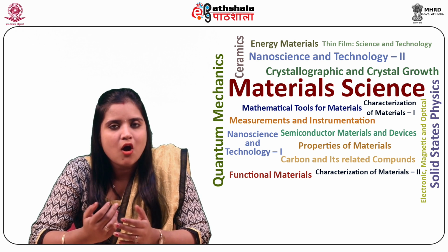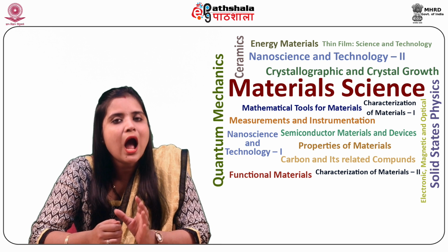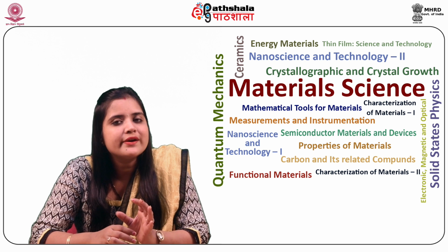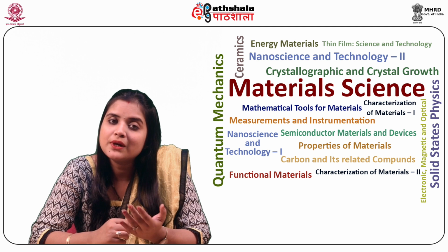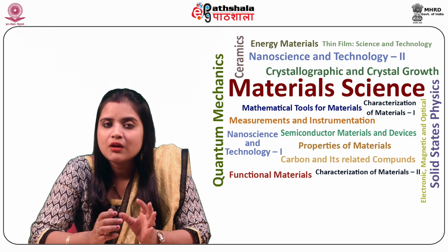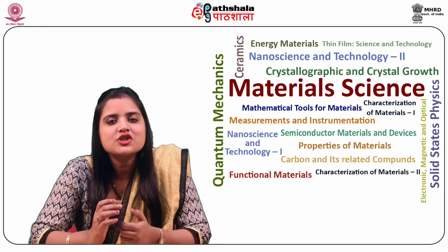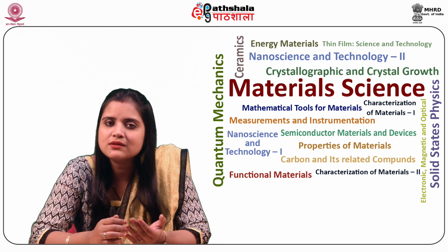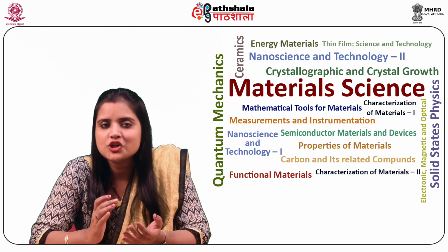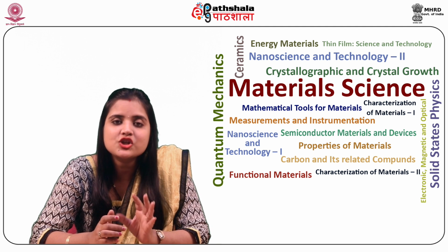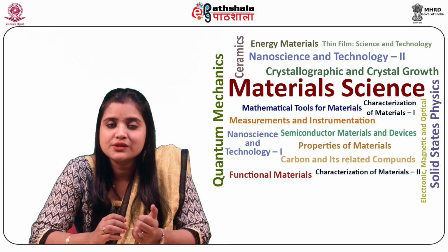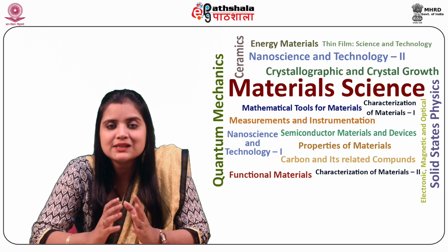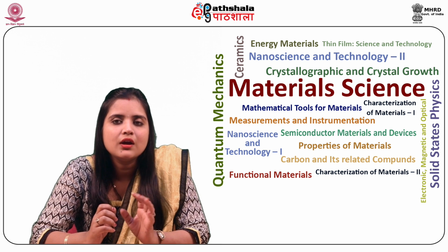Depending upon the type of application, materials with a high, medium or low magnitude of magnetic anisotropy are employed for respective applications like permanent magnets, magnetic recording, information storage media, or magnetic cores in transformers. It has been observed that the physical basis which dictates the preferred orientation of magnetic moments in magnetic thin films and multilayer structures can be fairly different from the factors that are responsible for the easy axial alignment along the symmetry direction in a bulk material.